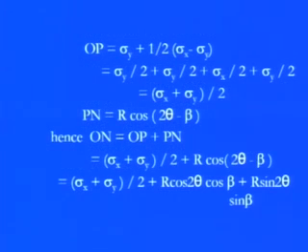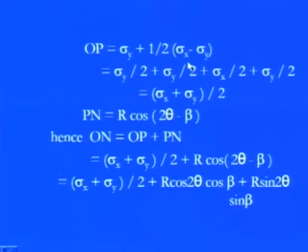We have discussed in the previous slide that there is a straight relation with the OP to ON. So we would like to see how, from the Mohr circle, we can get the value of the OP. OP is nothing but equal to sigma y plus (sigma x minus sigma y) by 2. Again, the biggest assumption we made here is sigma x is greater than sigma y, so sigma x minus sigma y gives a positive value. Taking these assumptions into consideration, OP is right from the origin to the center point, which is sigma y, the O to K, and K to P was (sigma x minus sigma y) by 2.